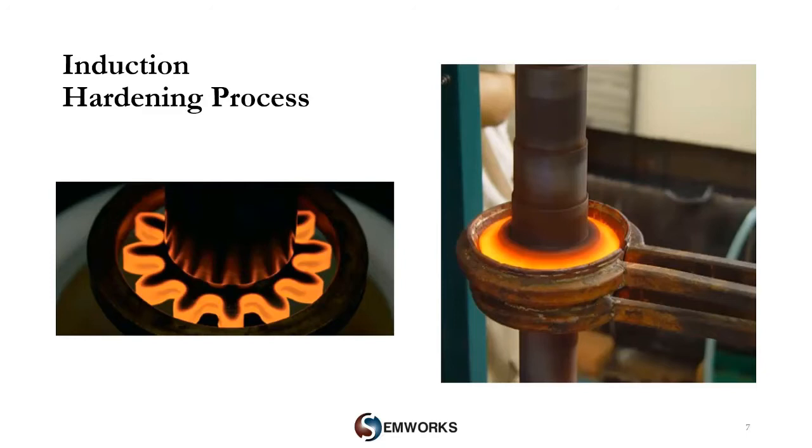Some mechanical parts which are frequently exposed to continual external stresses require hardening processing to provide optimal performance and long life expectancy. So induction hardening allows an efficient way to thermally treat gears, shafts, bearing tubes, pipes, etc. Induction is the perfect solution for many hardening requirements, like the fast heating rate, the uniform temperature, and the easy heating control.